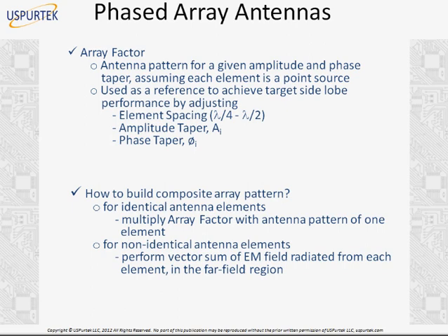antenna element. So what about using quarter wavelength is another question from Matthew. Yeah, of course, you can use quarter wavelength, but that is a limit. Beyond quarter wavelength, you will have more mutual coupling. So typically, we have a range here, a quarter wavelength to half, which is tolerable in case